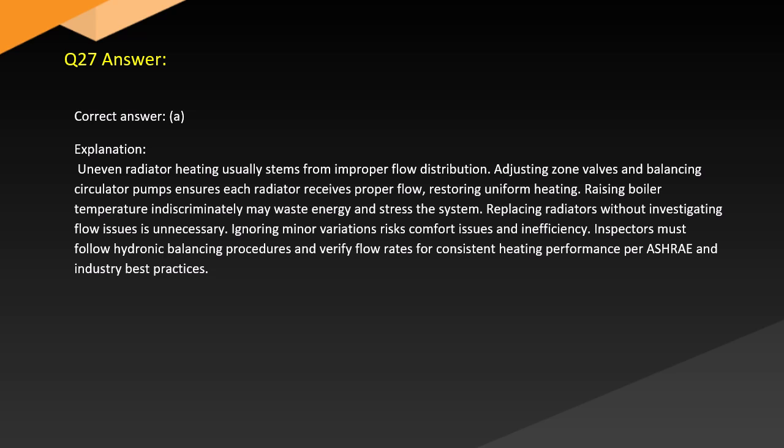Replacing radiators without investigating flow issues is unnecessary. Ignoring minor variations risks comfort issues and inefficiency. Inspectors must follow hydronic balancing procedures and verify flow rates for consistent heating performance per ASHRAE and industry best practices.